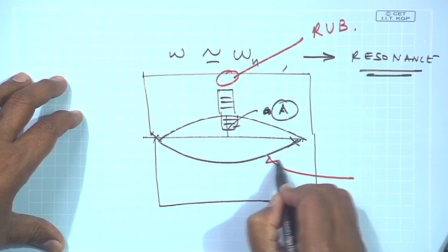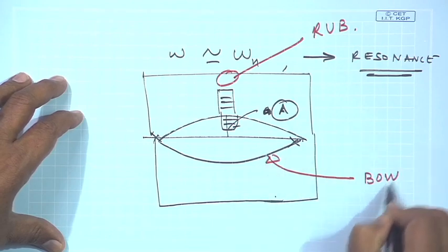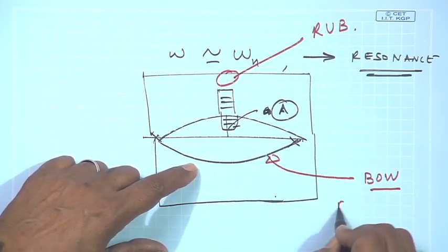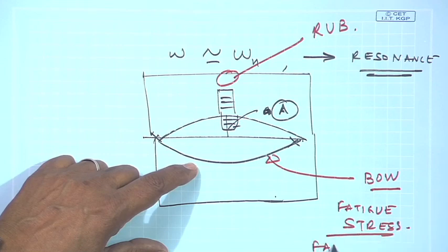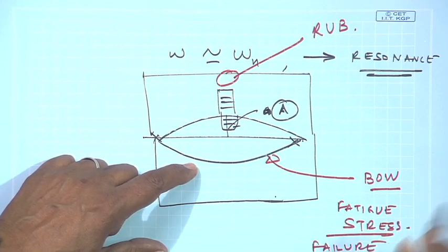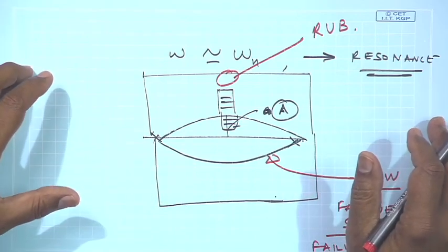If the shaft flexes too much, it could induce fatigue stress on the shaft, and there could be failure. This gives you an idea of the importance of understanding the dynamics of a rotating shaft supported on bearings, and all the designs associated with ensuring a stable design of the rotating system is what we will be studying in rotordynamics.